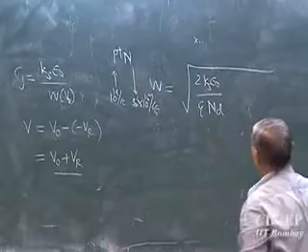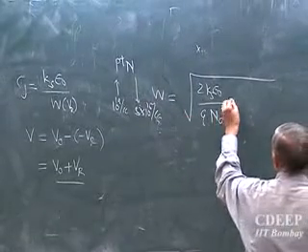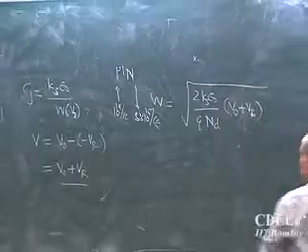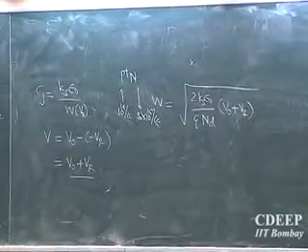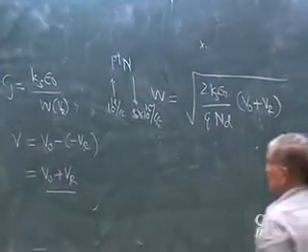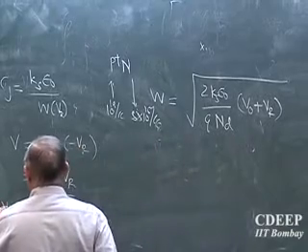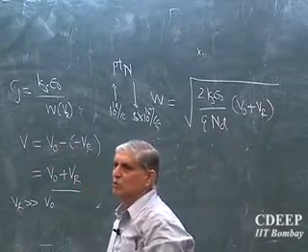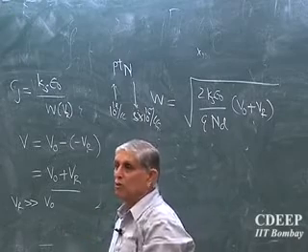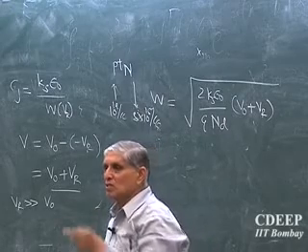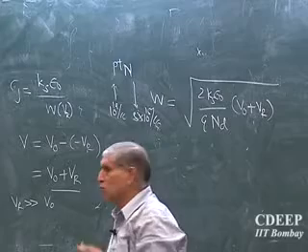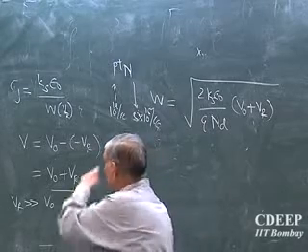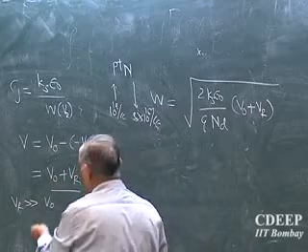So I can say this is smaller and then I can write V0 plus VR. In normal cases VR is much larger than V0. Reverse bias is tens of volts, 5 volts, 1 volt, at least more than 1 or 2 volts. V0 is typically how much? 0.6, 0.7 volts. So for analytical purposes you should write the correct formula, but numerically you may say V